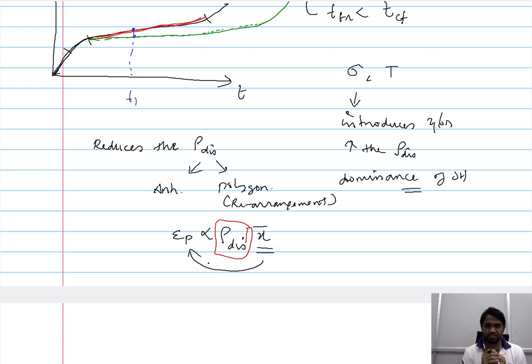So what we have is, in this steady state condition, even though it is marginal or minimal, there is a strain associated with the steady state condition. This strain is not caused by an increase in the dislocation density, because the dislocation density is significantly reduced by annihilation or rearrangement at the steady state condition. However, the existing dislocations keep on moving through glide and climb, thereby increasing the average distance covered by the dislocations. This increase in the average distance ultimately contributes to the strain observed, which could be minimal, but still there is a strain observed in the steady state condition.